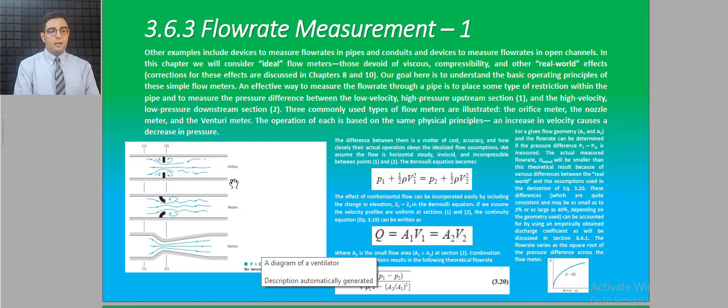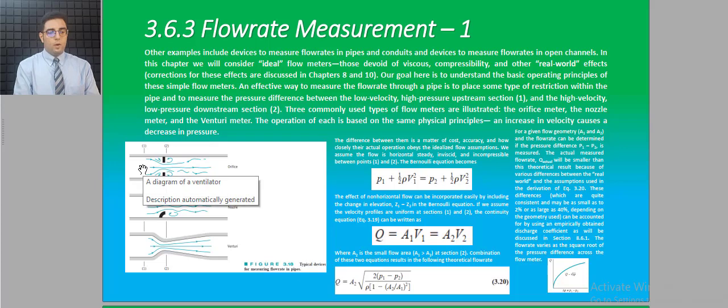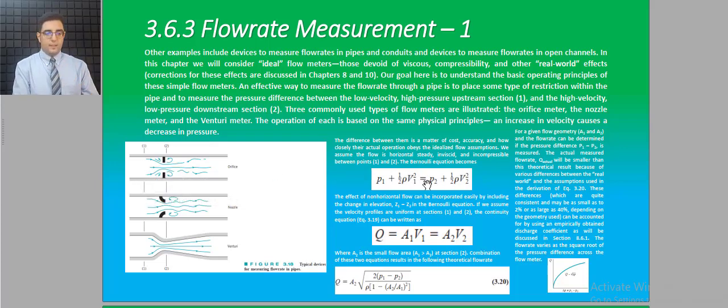If we apply the Bernoulli equation between point 1 and 2, we can have it as this, as we have no elevations. Where once we are considering a continuous situation, we have this equation either, which flow rate is equal to corresponding cross-sectional area multiplied by the velocity.